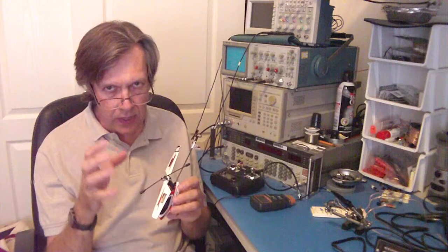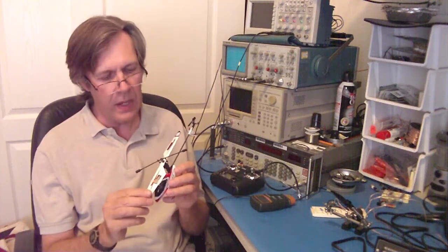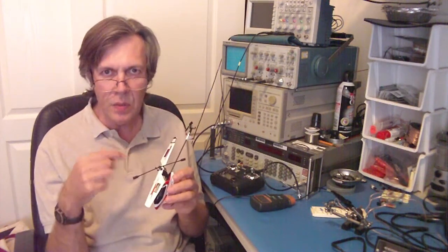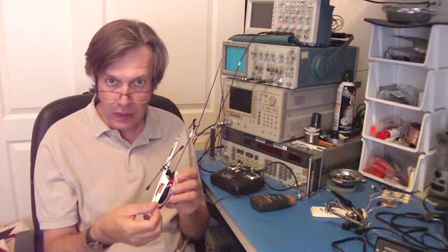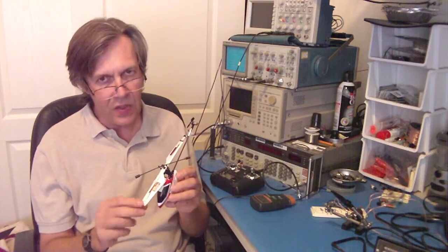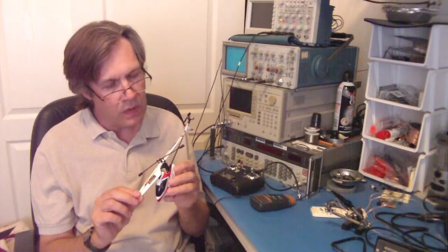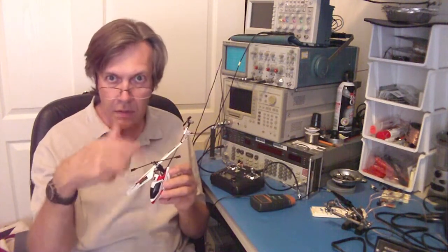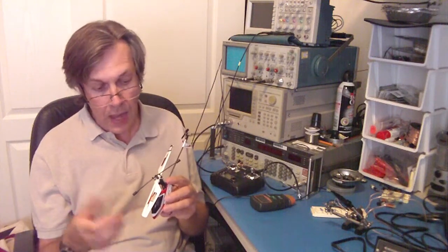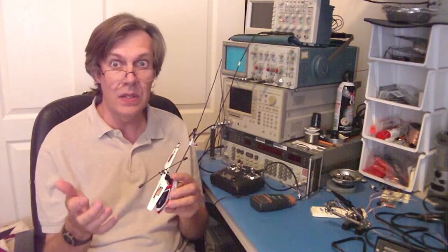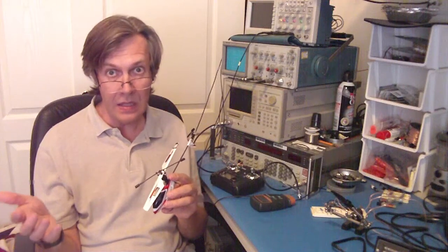And that's for when something happens at exactly the sample rate. In other words, when we get one full rotation for every sample, it's going to look like the blade's not moving. If it's moving slightly faster than the sample rate, it's going to look like it's moving very slowly, when in reality it could be moving quite fast. And how fast? Actually, in a sampled system, we don't know, and that's why aliasing is bad.